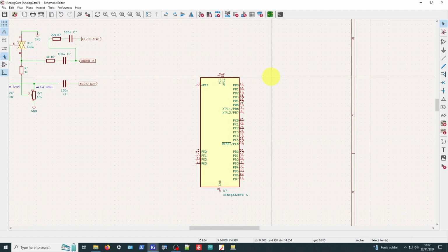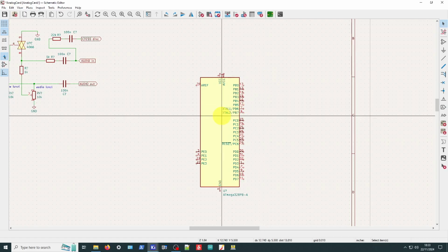The only thing is that you do end up with a little 6-pin DIL header, which doesn't really do anything except when you come to program the chip. The way I look at it is, why not just put the pins on the board, and then you can program it directly on the board without having to remove the chip and put it into a separate programmer. So that's how I like doing it. But you could use a 28-pin dual in-line package and just put it on a holder and pull the whole chip out to program it. So yeah, there's our chip, and now we'll do another jump cut and we'll get this thing wired up.